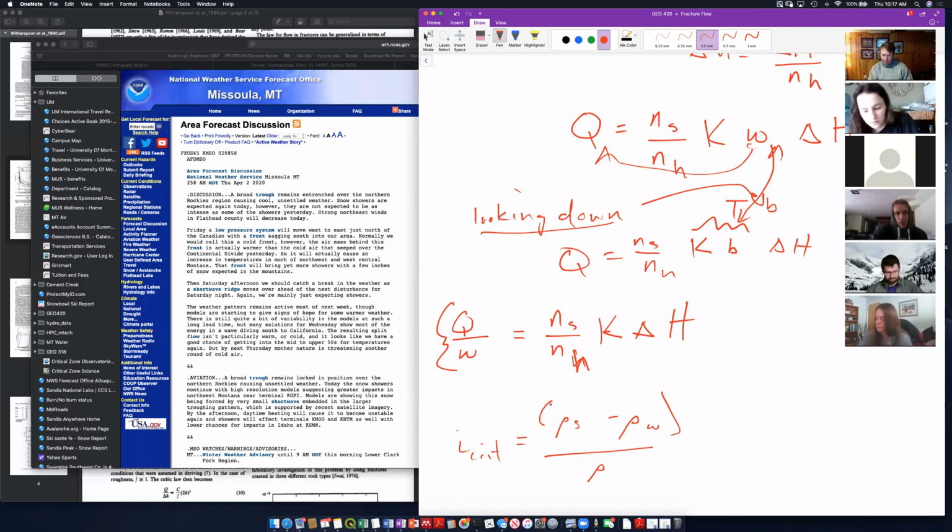So you calculate what your critical hydraulic gradient is, and that will give you some value, whatever it is. Then you compare that value to your gradient, DH over DL, in your flow net at point X.